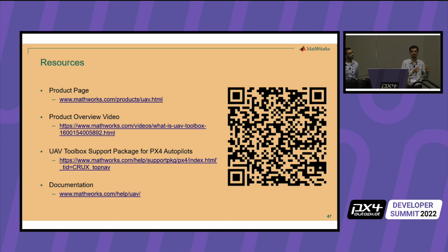It comes with the tool in Simulink. But if you want this customization, you need Unreal Editor installed. Inside it, you can bring in meshes for the scene as well as the platform, and customize everything. We also have documentation along with our tools to follow for this customization process.